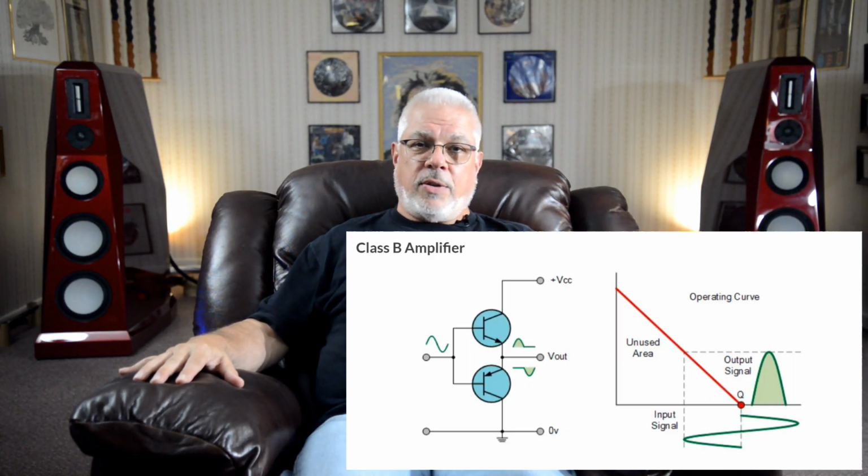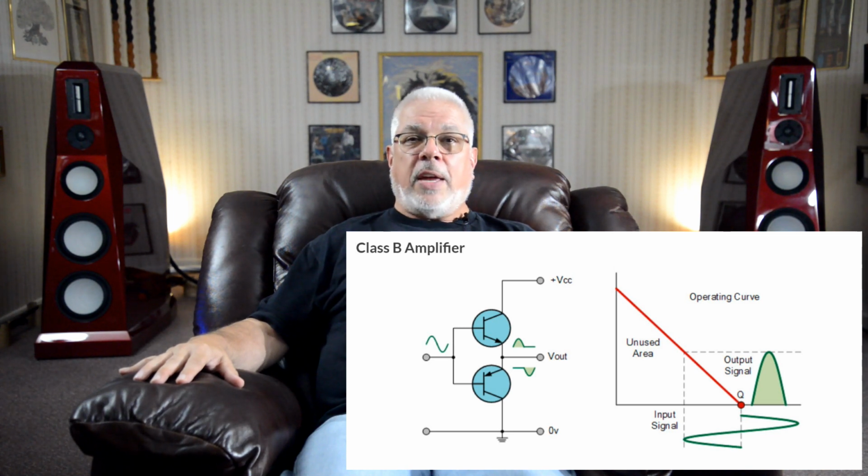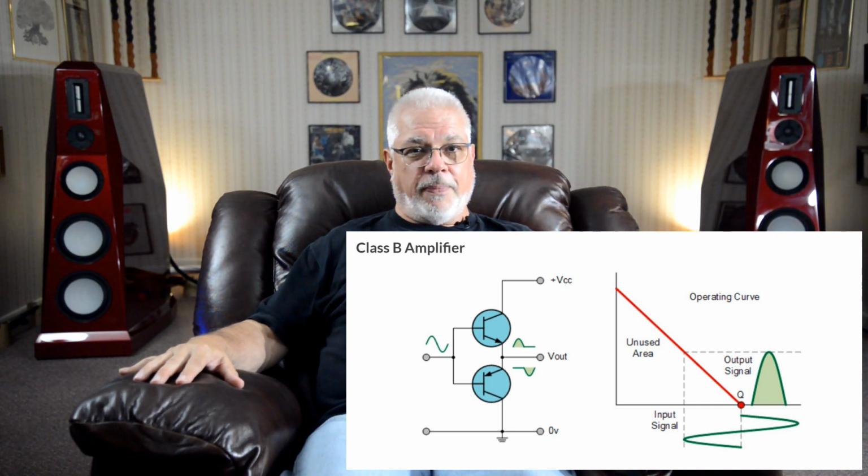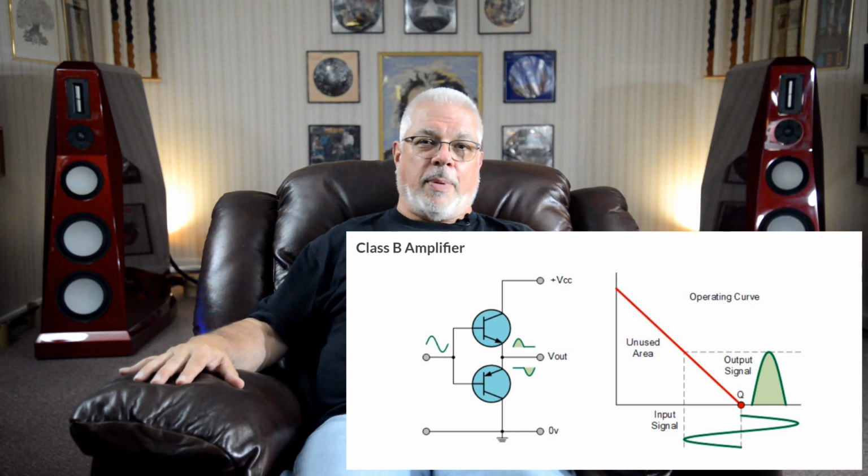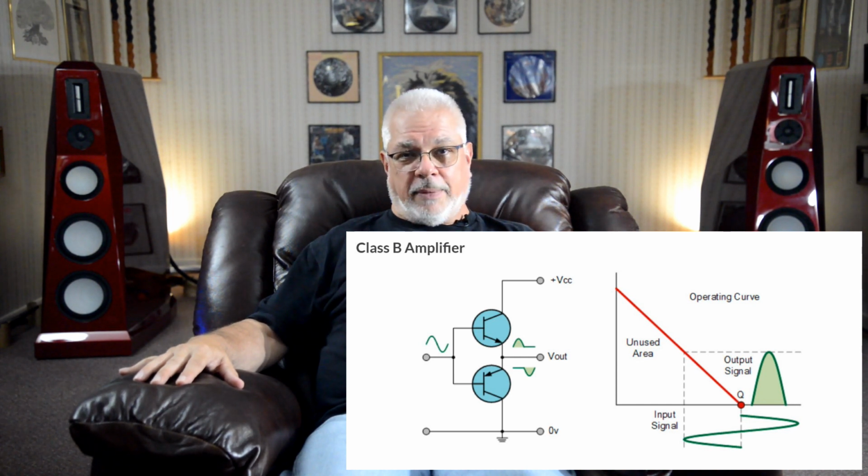Class B amplifiers are typified by having each of the complements responsible for only one half of the full output turn on during its duty cycle. It then turns off completely when it is done reproducing its half of the output and rests while the other complement runs through its duty cycle. When that second complement is finished and the drive signal swings back past the null point into the first complement's half of the waveform, it then switches back on again.